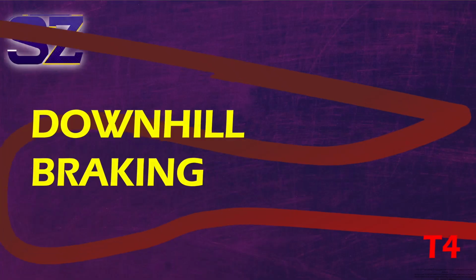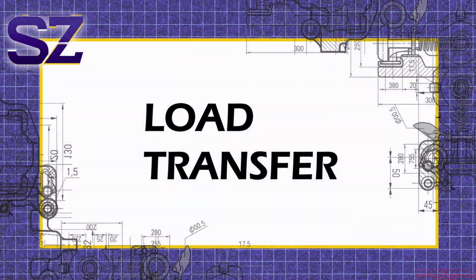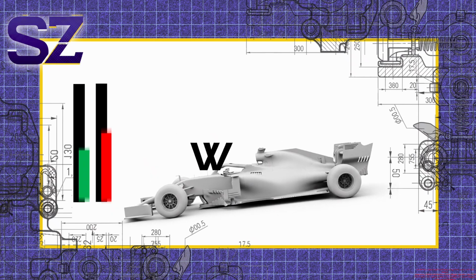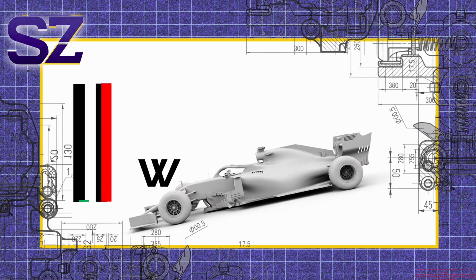Turn 4 at the Red Bull Ring is deceptively simple. A downhill braking zone into a medium speed right-hander. But from an engineering point of view, it's nothing but simple. There's a lot of physics taking place here. First up is load transfer. As the car decelerates, inertia shifts weight forward, and because turn 4 is downhill, gravity adds to that effect.